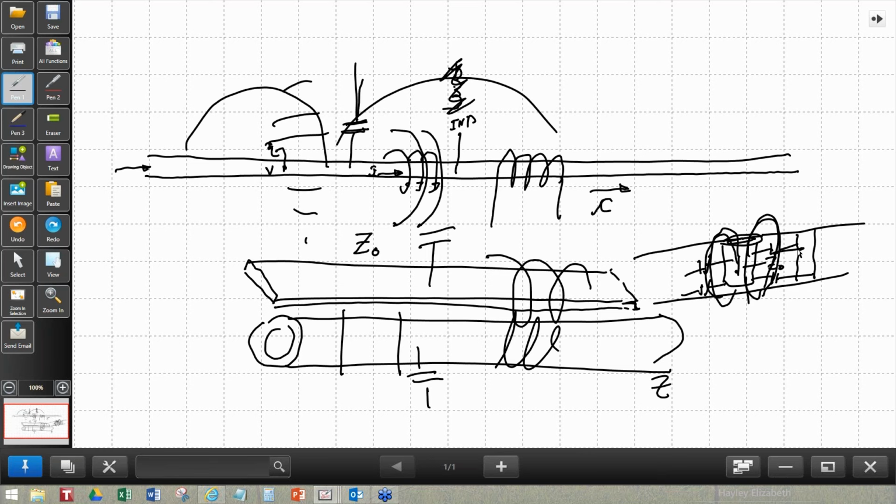Likewise, if you have a via very close by and you make current flow through one, and if the field couples from one via into the next via, you will basically induce current in the second via. So understanding this gives you an idea of, well, I need to be far enough away and shielded enough that I'm not going to be creating an electromagnetic problem.